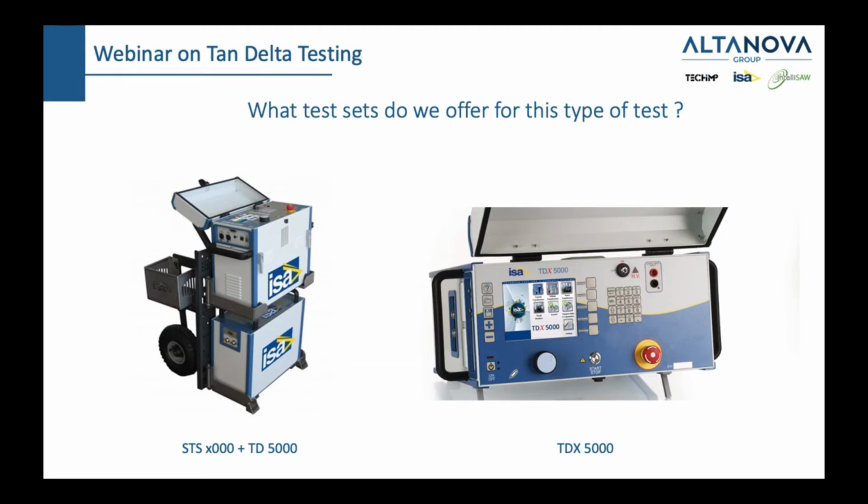Doesn't absorption current affect the results? I'm not sure I understand that. Please, can you explain a little bit what you mean by absorption current? What is the maximum testing voltage of a low voltage transformer? On the primary side, you would generate 10 kilovolt, and on the secondary, you would generate 0.4 kilovolt. And you will see that now.